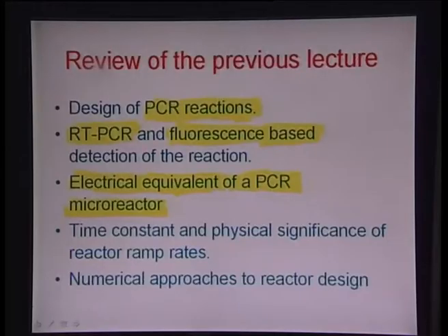Okay, so we talked about developing an RC model where we took thermal capacitance and thermal resistance, and derived an analogy between electrical parameters like voltage and physical parameters like temperature, which drives the process. We also looked at how the charge in an electrical circuit can be made equivalent to the heat flow in a thermal circuit, and then developed the time constant from that circuit point of view.